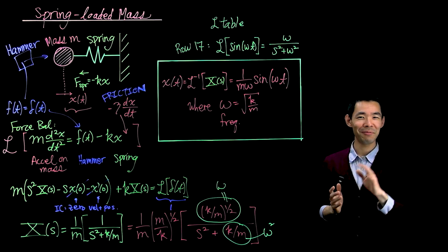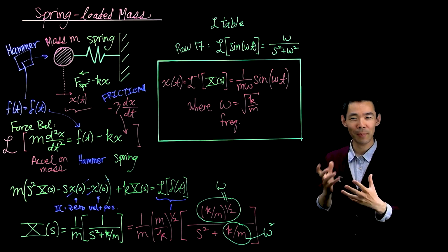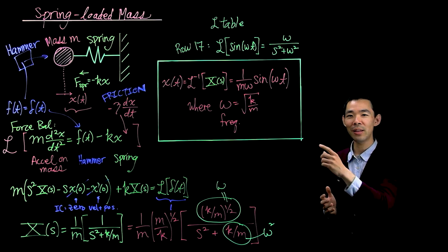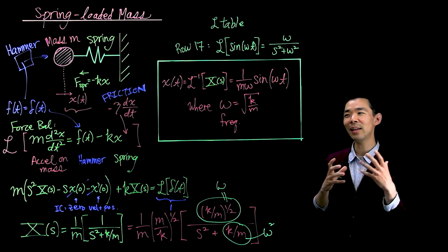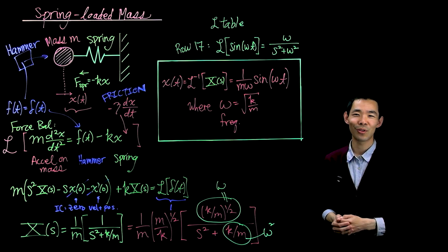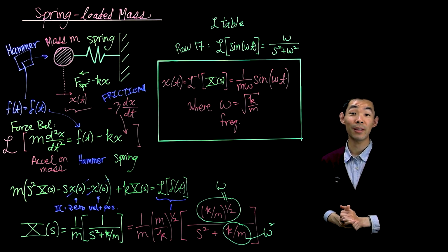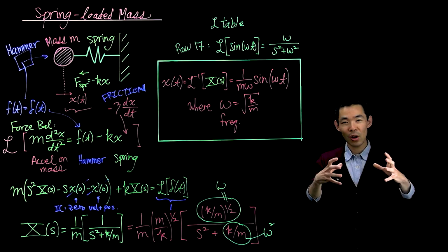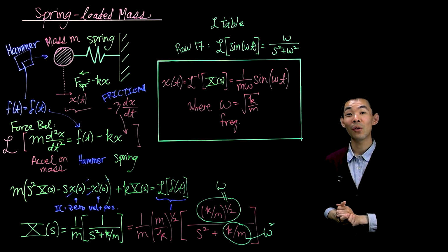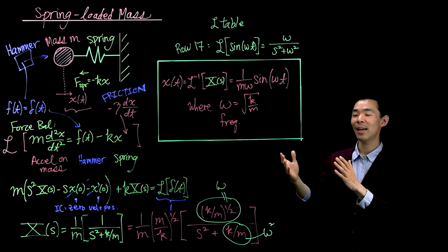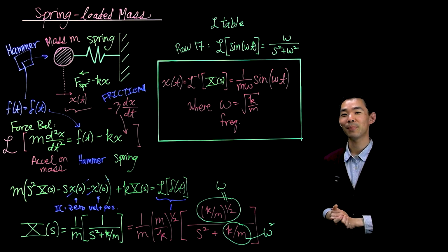Now, when we cover the entire subject of fluid mechanics, you'll learn that the way in which it depends on the velocity could be linear, it could be quadratic, it could be other dependencies, but the easiest possible case is linearly proportional to the drag. And in the field of fluid mechanics, it's called Stokes drag or creeping flow, where the motion is so steady and slow that the frictional coefficient is simply viscosity eta times the velocity, linear scaling as the speed.